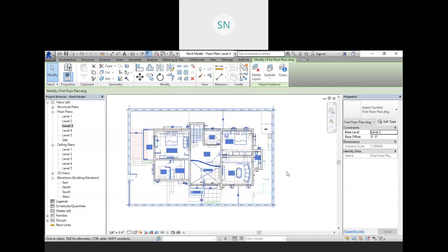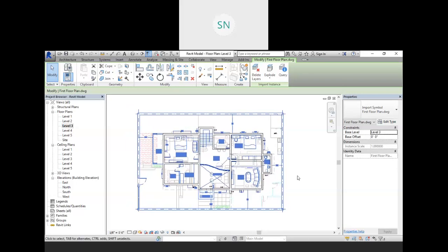So when we do our analysis, we do not need the entire 3D model. We just want that wireframe model and the cross section properties. That's why we use the analytical model for analysis purposes. So if you are doing modeling work, then use your regular levels. Analytical level is for analysis purposes. Okay.